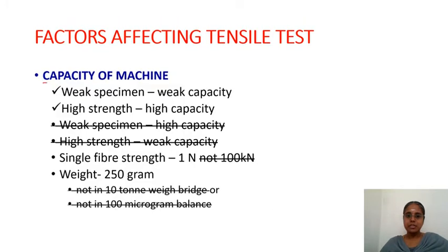Next is the capacity of the instrument. As I already said, if I have to weigh myself, I can't stand on a micro balance, and I should not stand on a weighbridge either. So you have to choose an instrument of exactly the right capacity.